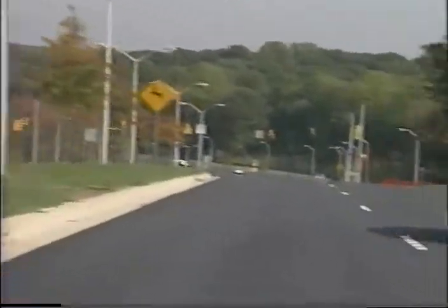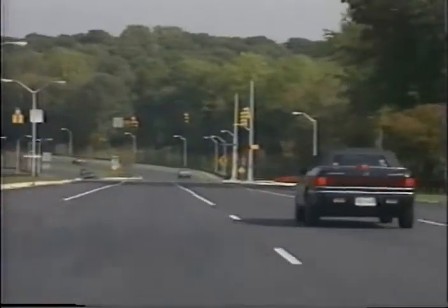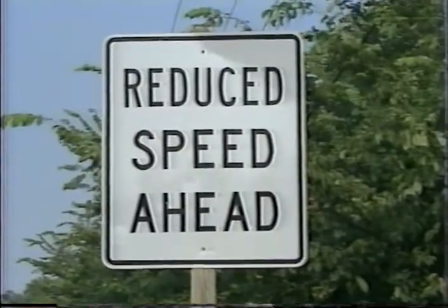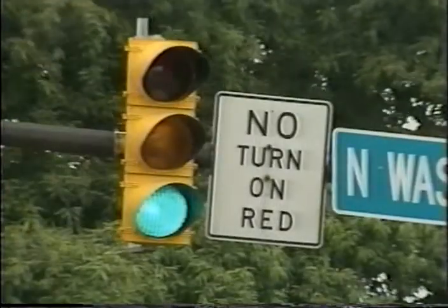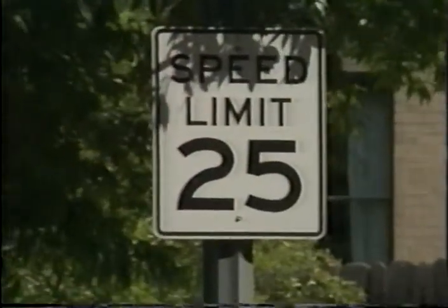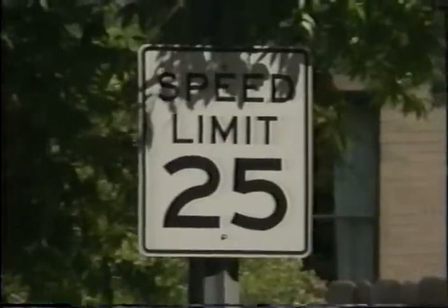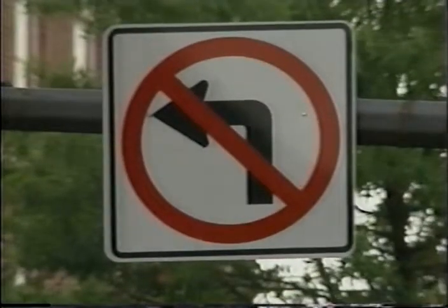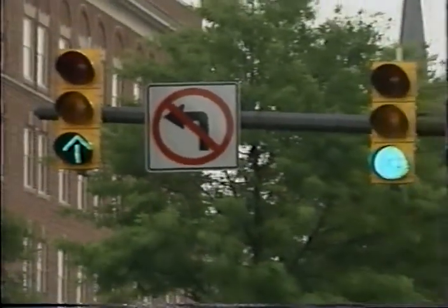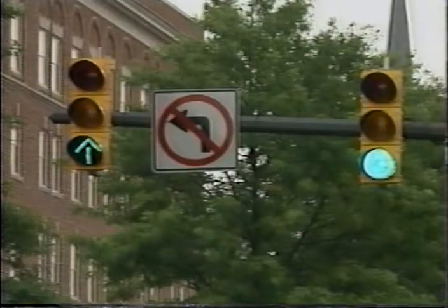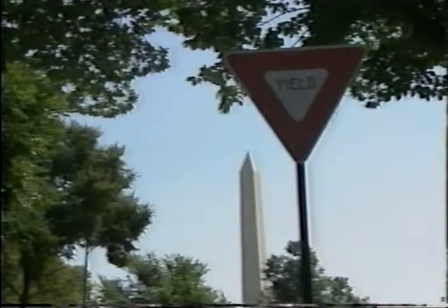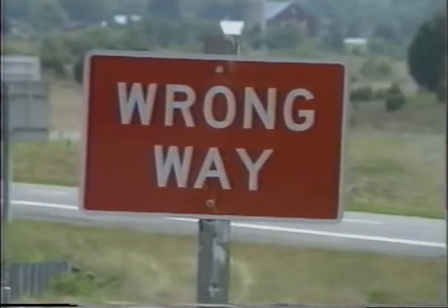Now, let's look at some differences and special considerations concerning each system. In terms of general appearance, in the U.S. system, regulatory signs are typically rectangular, with the longer dimension being the vertical one. The standard color scheme is a black legend on a white background. A red circle with a diagonal slash along with a black diagram means a prohibited maneuver. Red is used as a predominant color for stop, yield, do not enter, and wrong way signs.